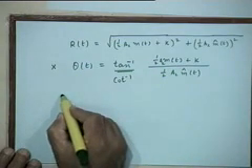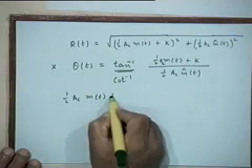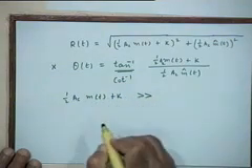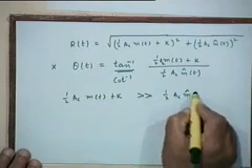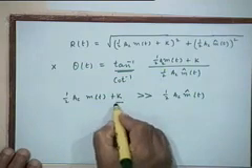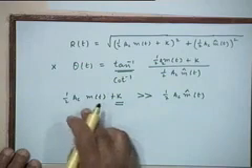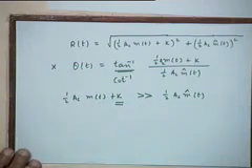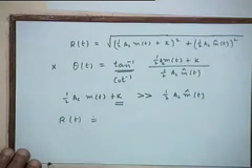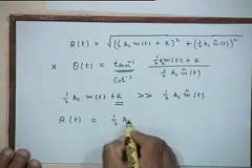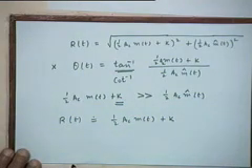so that this can be ignored in this squaring and square rooting process, right? So if we make the assumption that half A_c m(t) plus K is much greater for all time than half A_c m hat(t), which can be easily done by choosing K to be a sufficiently large constant with respect to these other signals, then we can approximate R(t) as equal to half A_c m(t) plus a constant K, right?